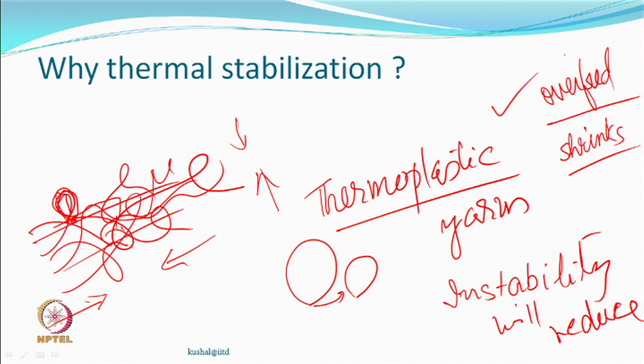Okay. So, now look at this drawing zone, you are obviously giving a draw ratio, stretching. Air jet texturing zone, you are overfeeding. Mechanical stabilization, you are stretching. In thermal zone, you are overfeeding. So, you are not making life easy for anyone. Theoretically, everywhere there is a parameter which can be controlled. In drawing, parameters have to be controlled. If you go to heat stabilization, that parameter has to be controlled. Mechanical stabilization, that parameter has to be optimized.